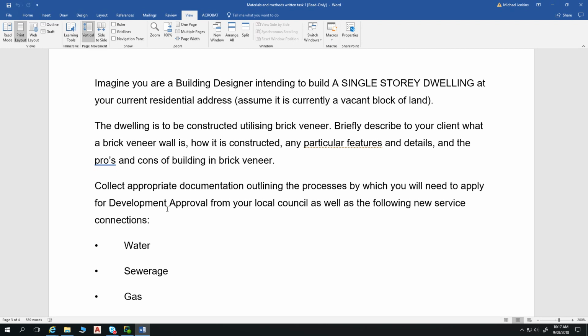And then we have this little piece here which is called a rebate. That is typical to brick veneer construction and most forms of veneer construction. What a veneer is, is an outside skin, an outside coating. So you can have a wood veneer on a bench top, for example. It's an outside skin to what is considered the main element.